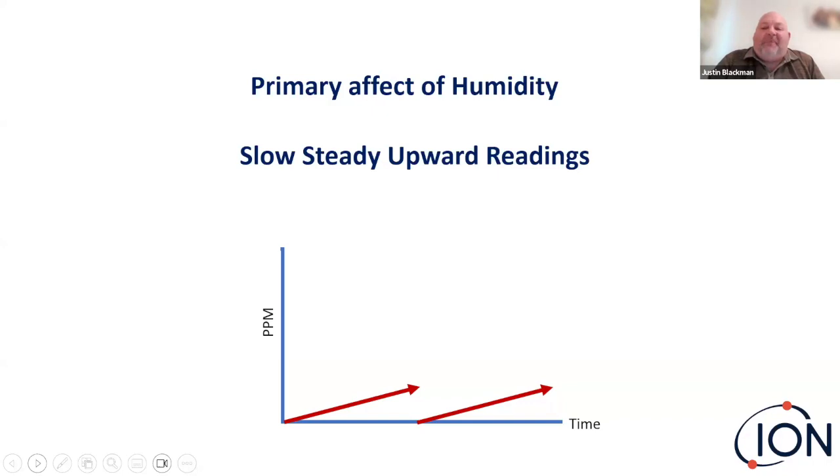They would do all the best things they could. They would test their handheld PID using a cylinder of calibration gas. They would do a bump test and get a perfect 100 reading. They would apply 100 ppm of isobutylene, and the instrument would read 100. They would go out into the field that day full of confidence that their instrument was working wonderful, 100% ready